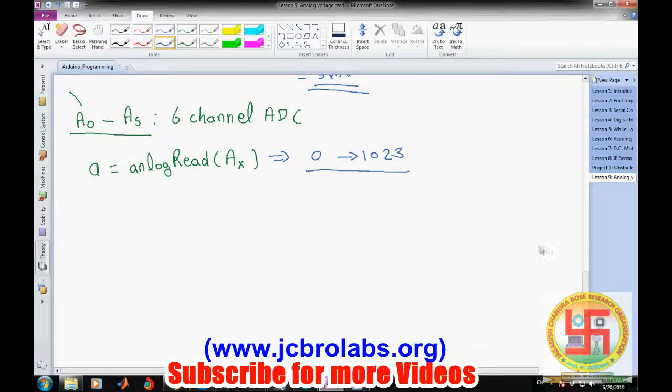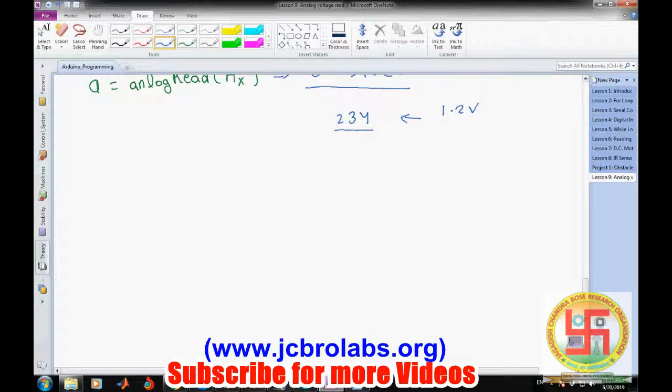Okay, so now many times this may not be well suited to you. Say we are using 1.2 volt and it gives an output of, let's say, 234. You may be scratching your head, okay, what does this 234 mean? So you need a kind of mapping, like for example, from this 1023 you want to convert it back to 1.2 volt directly. So for that, the mapping is known as the digital to analog voltage conversion. It is not hardware, we are doing it in software only, through a mathematical formula. So this conversion is very easy, or we can say it is known as the mapping.